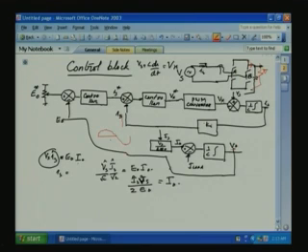There is not much variation in the IS. So, the peak value of the IS reference comes from what we give here. We have to give a sinusoidal reference here. With that sinusoidal reference, IS should be in phase with our mains voltage Vs. That will take care of the unity power factor.